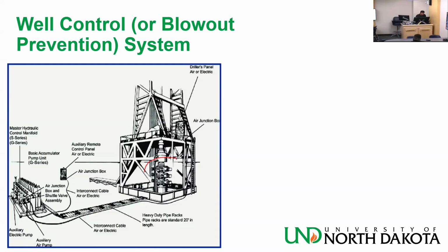Okay, these are the BOPs. They are below the rig floor, the dirty place to be. They are usually colored red. They are very important. They need to have a certain configuration. You decide on what kind of configuration you want it to have. Oh, sorry, I have the thing hanging here. Let me move it. Now they are operated. This is what you use to shut in the well. When I said the well is shut in, you use the BOPs to shut it in. You apply high pressure on those rams and you close the well.